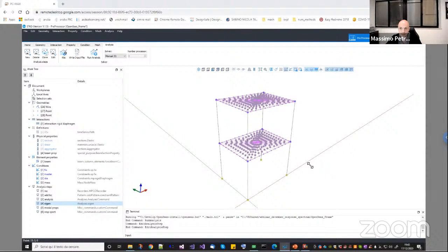it uses the tangent stiffness. So in theory, it should take into account the fact that one of them goes into tension and has a 0 stiffness. The problem is that this is kind of strange. I will show you later on what happens when you do an eigenvalue analysis during a nonlinear analysis.